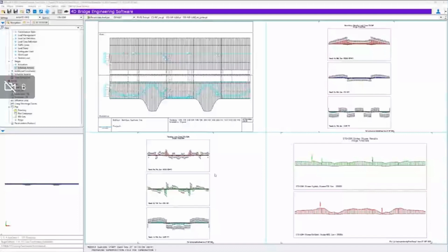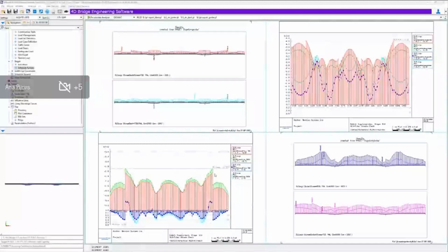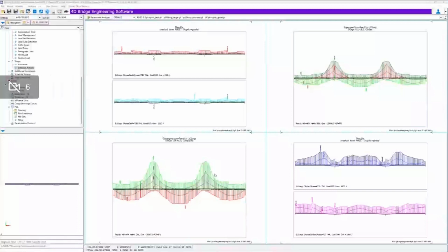So we can see the final stress state on the I girder for the service envelope with the two types of diagrams available to the user. So by RM sets definition at the top right and bottom left, and the other two by plot containers definition. And we can see now the ultimate capacity check results with the diagrams for the longitudinal bending moment MZ on the I girder top right with the split results, and bottom left for the composite section with joint results.